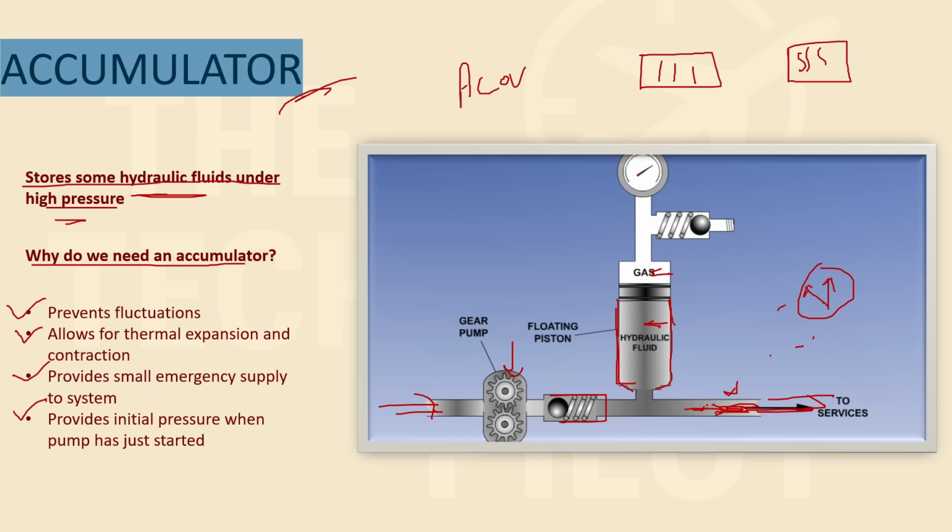We want it instant. We don't want the pressure drop to happen. We want, as the fluid contracts, there should be something that can immediately supply the extra fluid, right? So that's why we have this accumulator over here. So, for example, a little bit of fluid contracts here, so this accumulator will provide the hydraulic fluid,